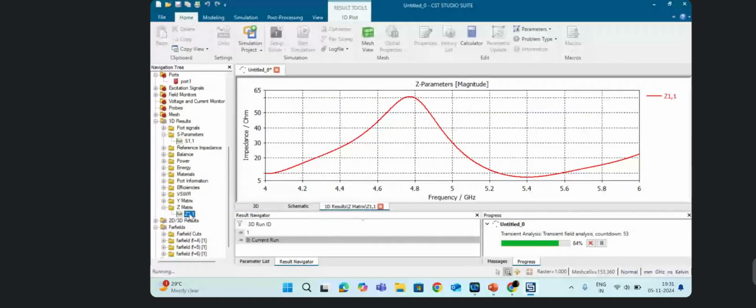And then when I say the impedance match, your antenna will radiate electromagnetic waves once the impedance gets matched. Okay. But the antenna should be purely resistive. Right? What is impedance? We represent impedance as R plus JX, right? We have the real term as well as the imaginary term. The real term is your resistance, the imaginary term is your reactance. Our reactance should be 0 and our resistance should be high. Right? So here you have the impedance matrix.